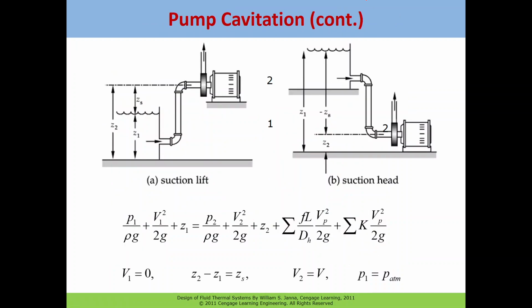These are the terminologies. Some other forms in symbolic terms: this is when the tank is below the pump level, so this much is the difference from the pump. Here we are not talking about a discharge tank, there is no discharge tank here. So here we are talking only from the pump center line. This much is below the pump center line, so we call it the suction lift, not the suction head, because the pump has to lift the water. So this is suction lift.